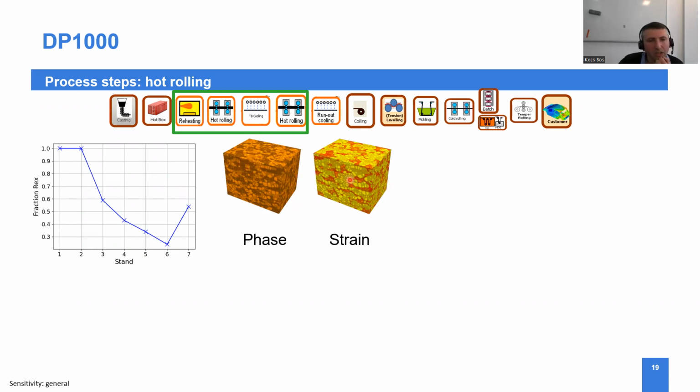And actually, I think this is something important that we have to point out: why, especially for advanced high strength steels, this type of full field modeling becomes interesting and important, because we see that recrystallization is not complete. This is a bit typical for these more heavily alloyed grades where we have higher levels of manganese or other substitutional alloying elements, which means that typically recrystallization goes slower.